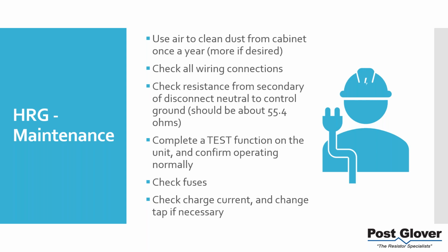Check your wiring connection once again. You always want to check the resistance. I would say most of the time you're going to have issues on startup. Somebody made a bad customer connection, or obviously we could make a mistake. I'll be honest, it's not very common with wiring, but we could do that. Or if there was an OEM that was installing it, they could have installed it incorrectly. So those things, you really should make part of your startup as well as your maintenance.